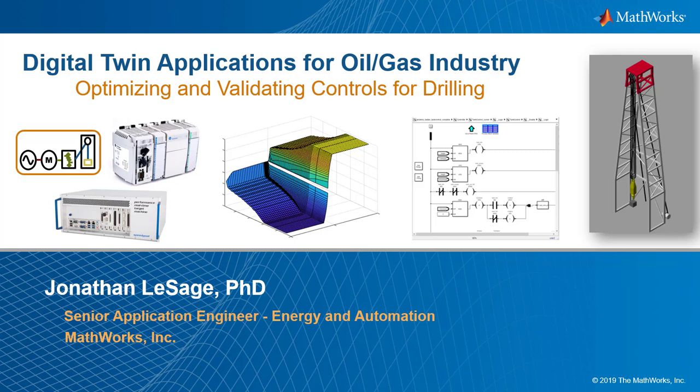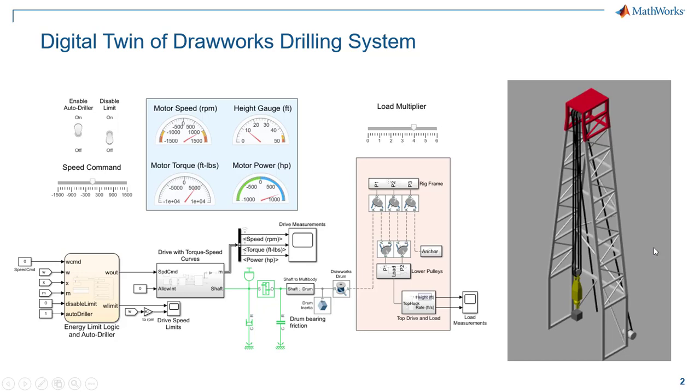In this video, we're going to start to take a look at how we can take a lot of the work that we've already done in that Stateflow chart that we've created, where we've built an energy limiter and auto driller logic, and actually deploy it outside of the simulation environment. And the way that we're going to do that is through code generation.